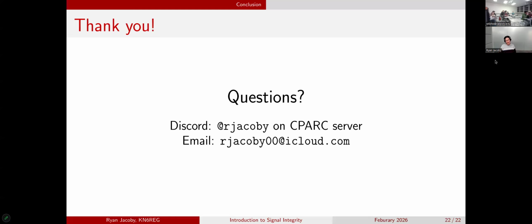Also, you don't want any extra trace length. As I talked about before, the higher frequency you go, the less distance that this voltage fluctuation actually physically occupies, right?